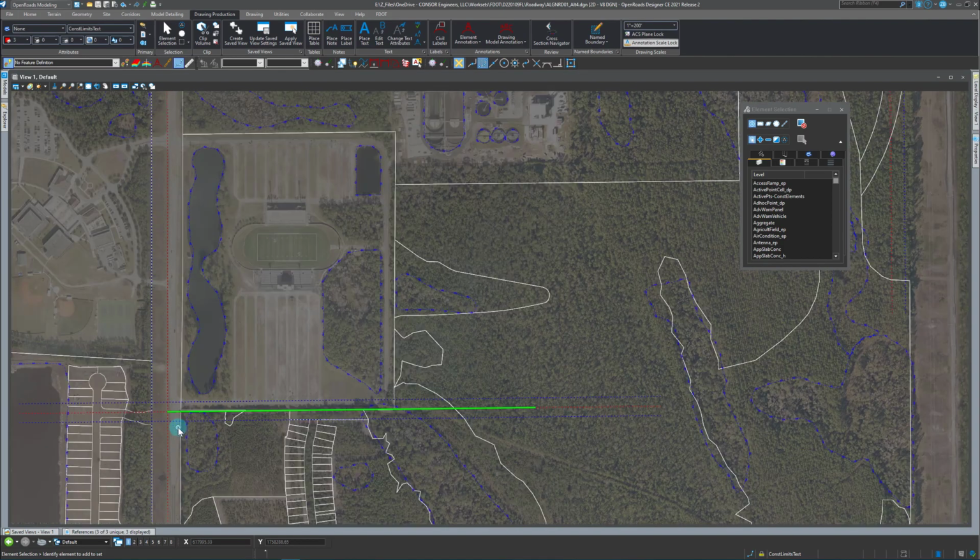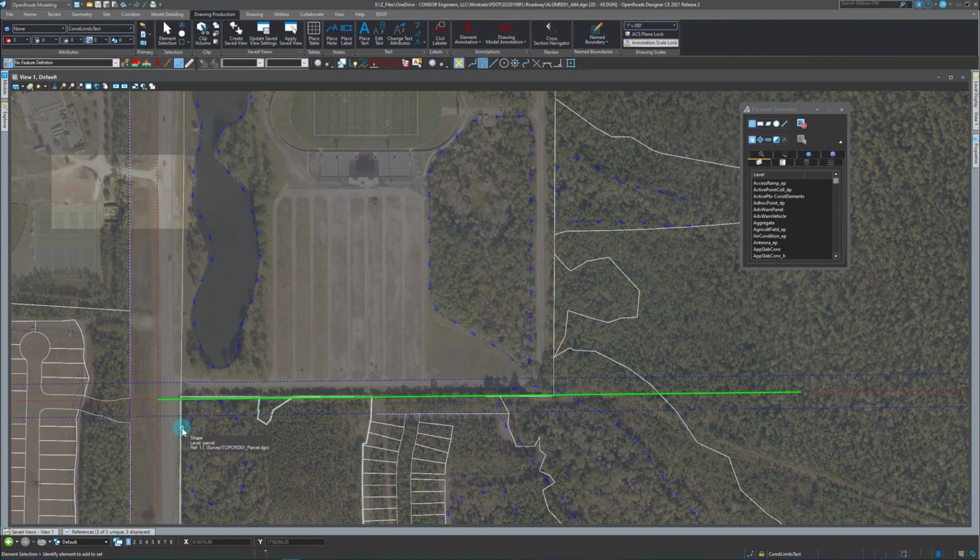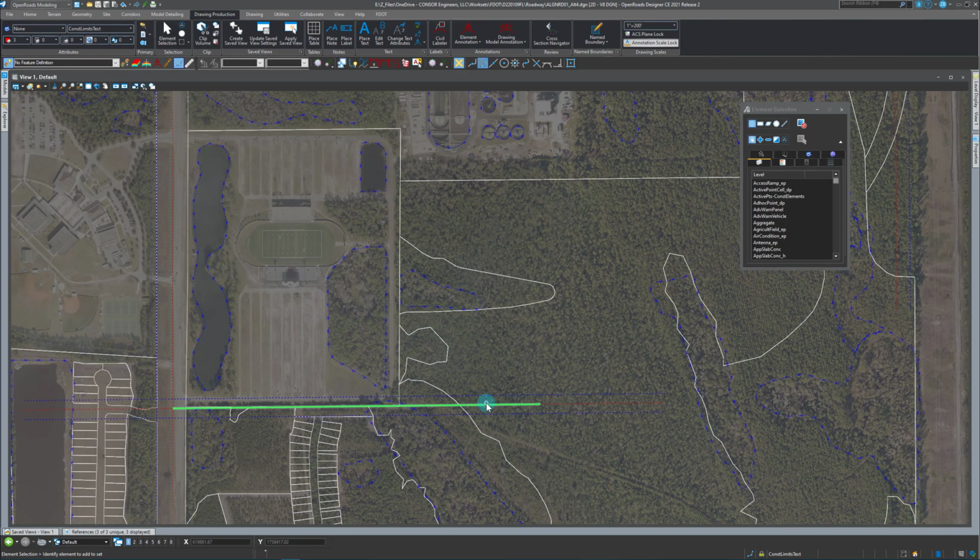So what I have to start is some sample plans or some alternatives that I'm referencing to try and lay out the alignment for. So really what I did is, started with my construction line like I did before and offset that 57.5 based on the plans. They've also told me the bearing of the alignment from that, so I match the bearing here.